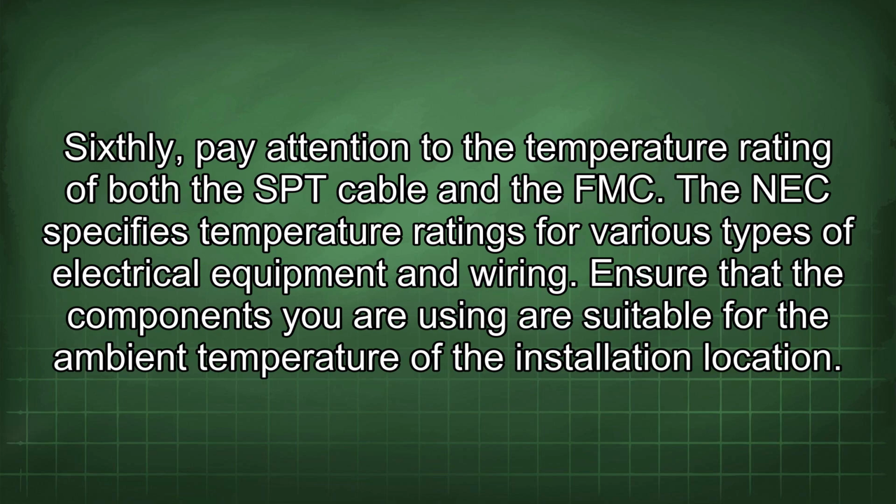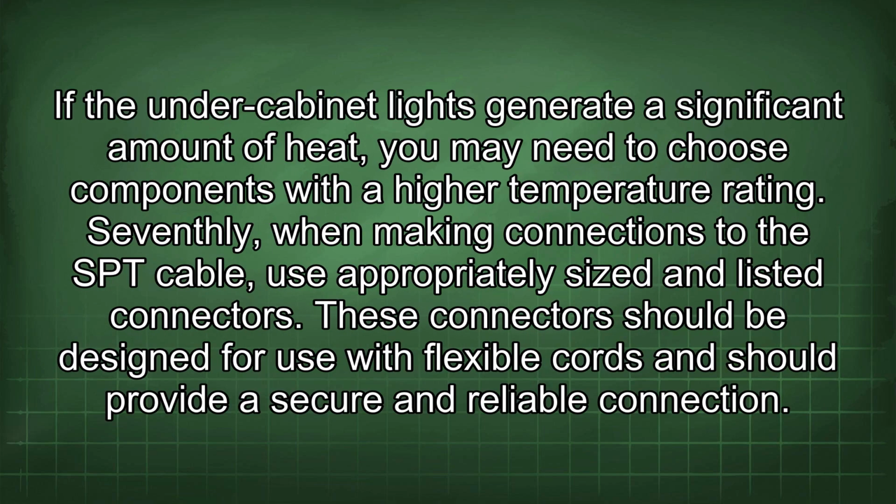Sixthly, pay attention to the temperature rating of both the SPT cable and the FMC. The NEC specifies temperature ratings for various types of electrical equipment and wiring. Ensure that the components you are using are suitable for the ambient temperature of the installation location. If the under-cabinet lights generate a significant amount of heat, you may need to choose components with a higher temperature